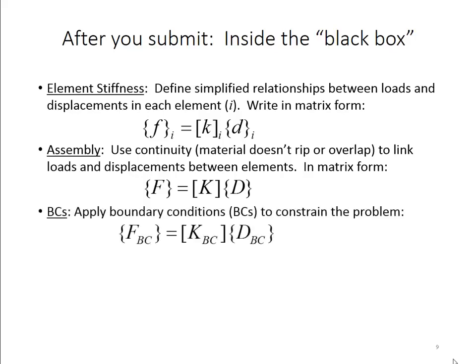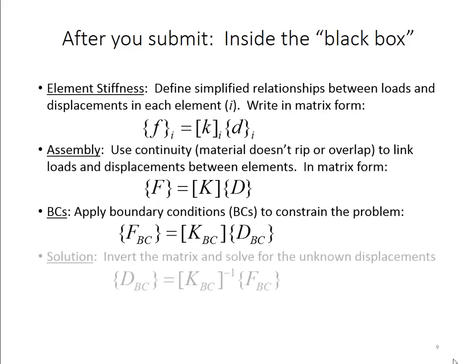Then you apply some boundary conditions. So you specify what points are actually known displacements. And when you do that, for computational reasons, we actually modify the stiffness matrix, the displacement vector, and the force vector, putting the BC for boundary conditions in each of them. We'll talk about this later on in the video series.